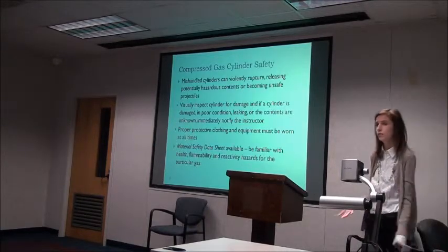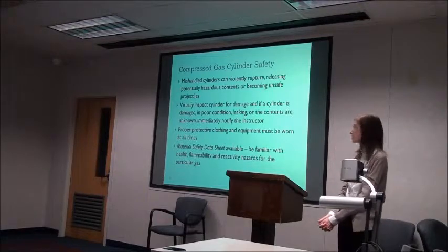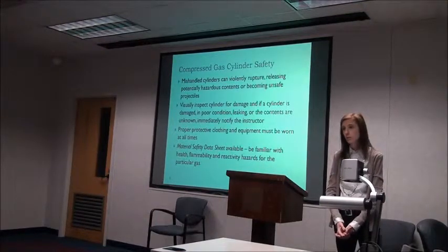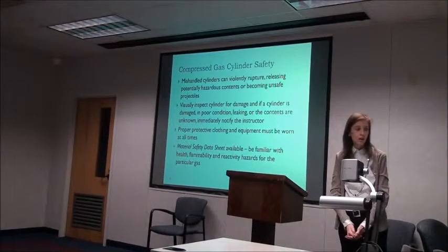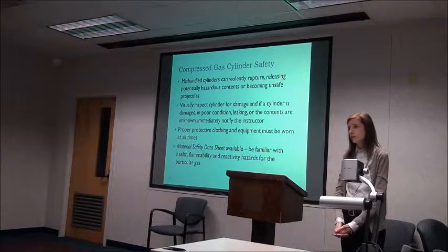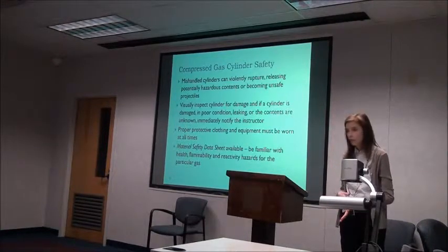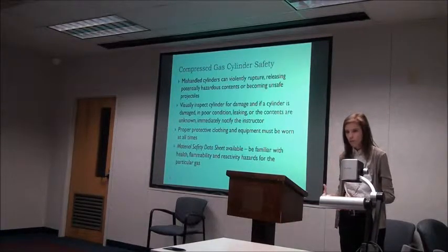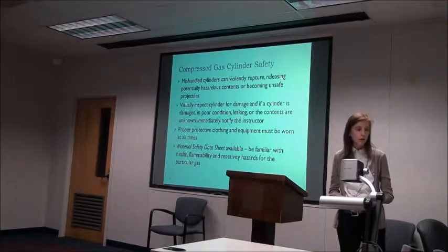I'd just like to continue with some safety about compressed gas, and when we're working with compressed gas cylinders. Mishandled cylinders can be very dangerous. They can release potentially hazardous material, or they can become a flying projectile. Whenever you're using a cylinder, make sure to visually inspect the cylinder. If it's leaking, or if you don't know what the contents are, or if it looks potentially dangerous, notify your instructor right away and don't open the valve.